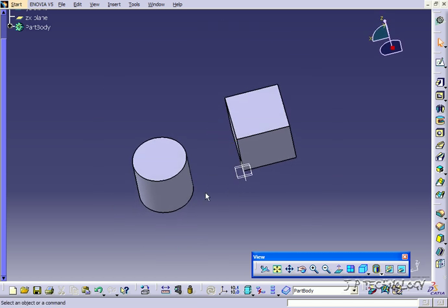So what the hole feature will do is it'll allow you to create many different types of holes without actually sketching it out or cutting and extruding and doing everything else. You're able to do all of the holes directly from the hole feature, and it gives you all the options, so it saves you some time from sketching everything and piecing together each different type of hole. So to start off, let's click hole, and let's click a face we want to put a hole